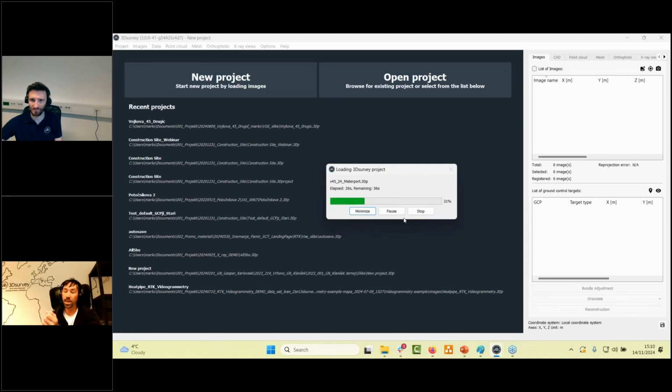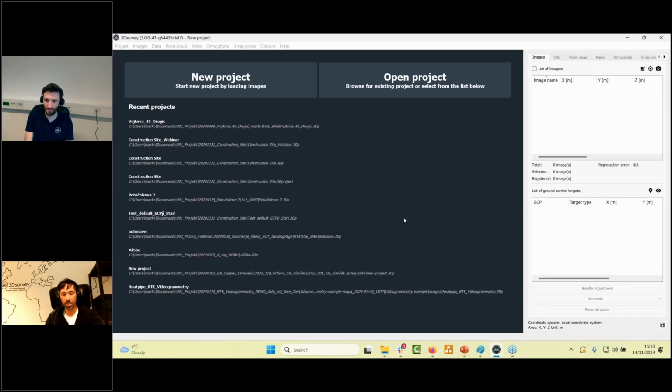You're not going to be able to calculate 3D models with the help of 360 images, because when we did those tests, the accuracy and the noise is quite big, because those are not very powerful images with the resolution and everything. But it's a super effective combination when you observe the spherical images and see the point cloud behind, and you can actually draw on image, on spherical image, and snap on point cloud. And this is kind of powerful, and this will be part of the scan module in the next release.